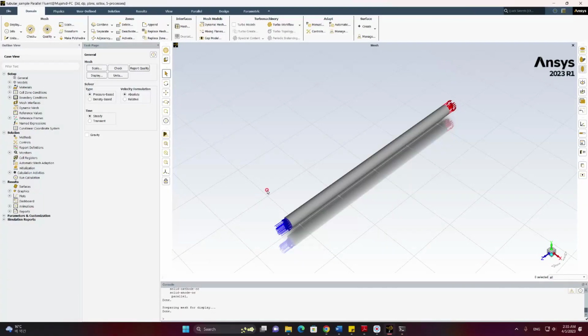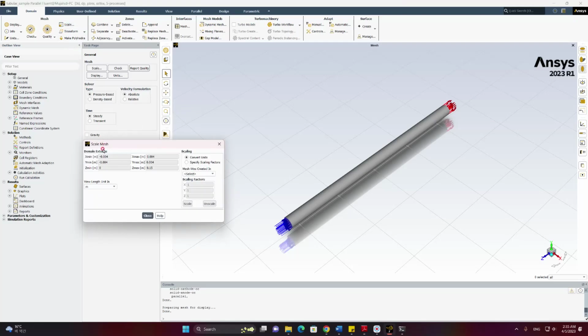So we have completed the first task, that is to import the mesh or read the mesh and display the mesh. So the next part is to check the scale. Check the mesh scales. And how to check the mesh scales? If you go to the scale option in the top ribbon, you can see everything is perfect. The lengths are accordingly 0.004 minus to plus, so everything is as required. This is normally good practice once we make our own model.